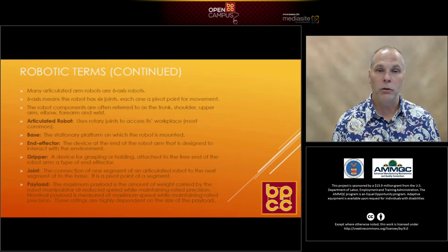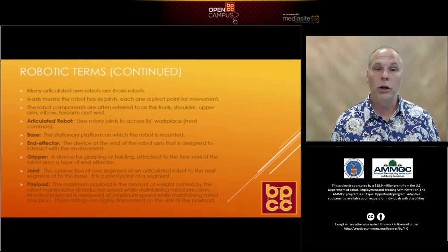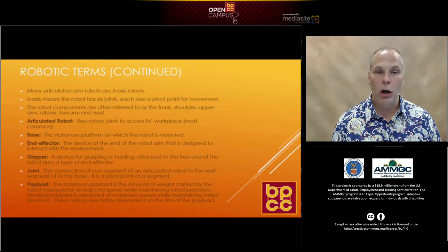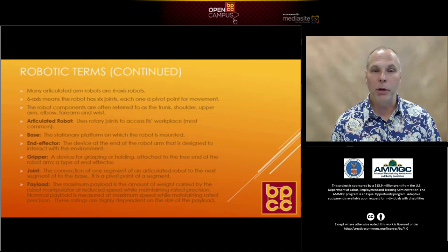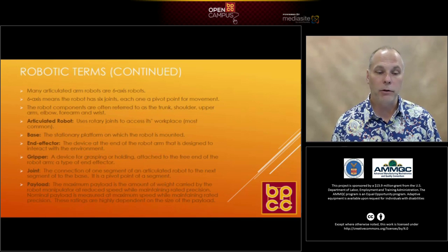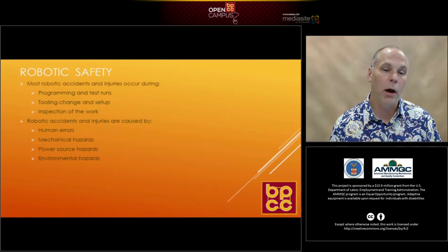Well, it's a 2,000 pound, it's a 1-ton unit. Means that the smallest rated mechanism of that robot is 1 ton. It can't pick up any more. It probably could, but you'd be worried about breaking a piece. Safety factors built in, those kind of things. So understand what a payload is when it comes to robots.